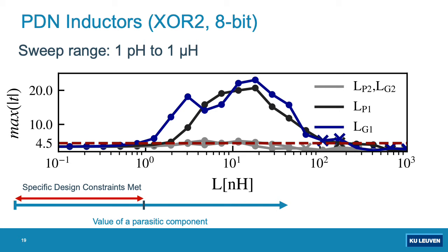Nevertheless, remember that our target circuits require orders of magnitude smaller currents than a full design. Therefore, the critical inductances could fall below the ones needed to meet the design constraints in a real design. Again, we're just trying to see what could go wrong. In our opinion, this shows that layout phenomena need to be taken into account when doing pre-silicon evaluations.